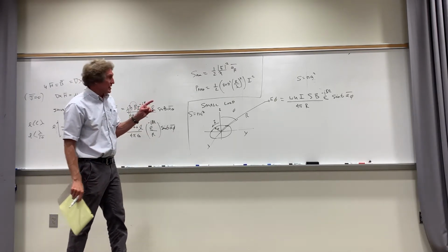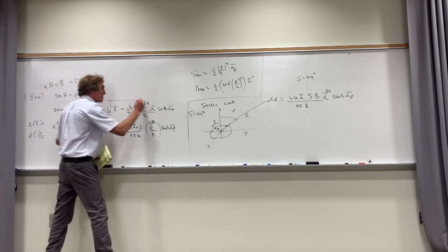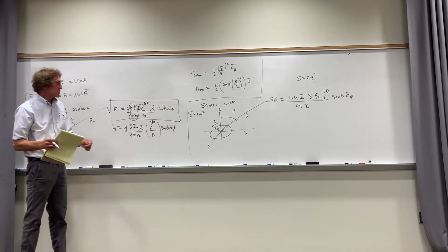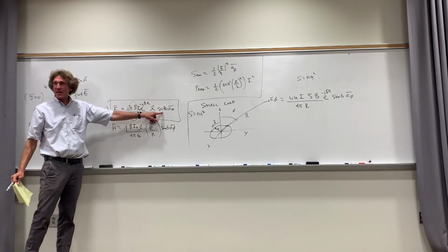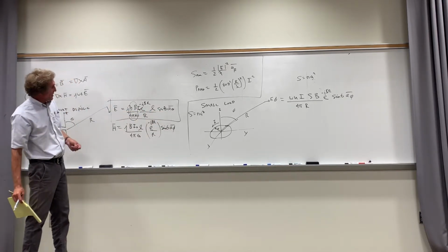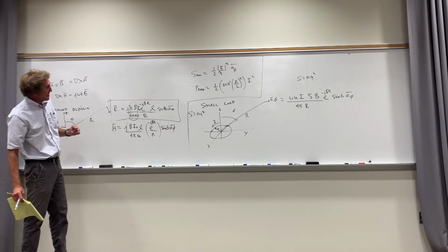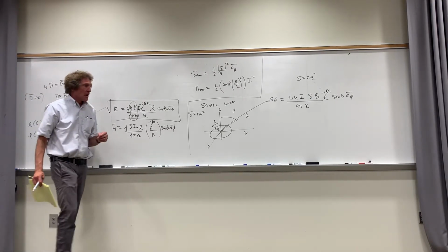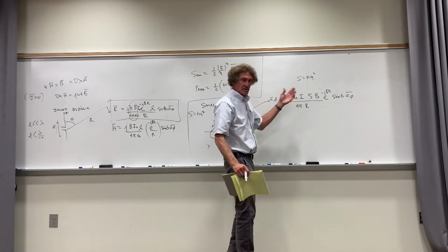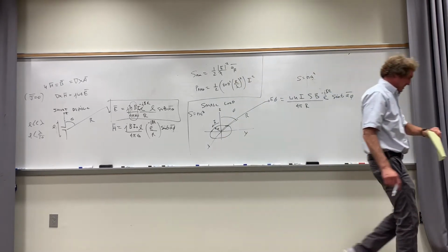Now, when you look at that, and you look at the short dipole, here's the electric field for the short dipole, right? You'll notice it's proportional to the current. It's a function of the sine of theta. You all see that? It's proportional to sine theta, inversely proportional to r, proportional to current. The other stuff around here are just relative constants. Now, a couple things I want you to notice about this.